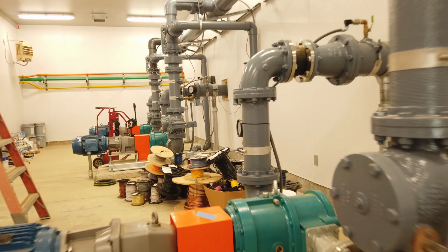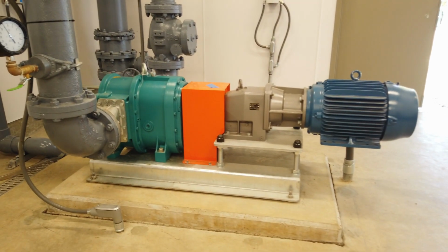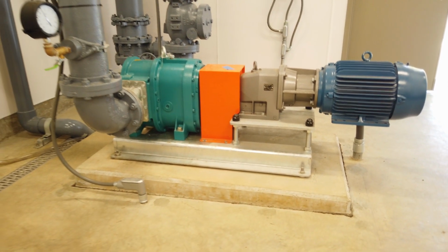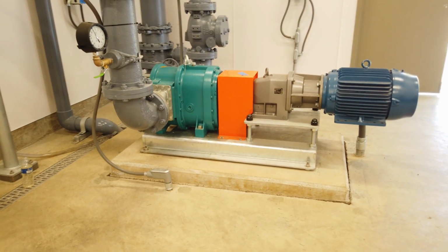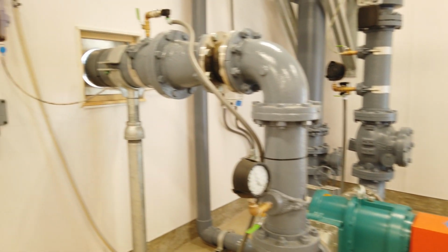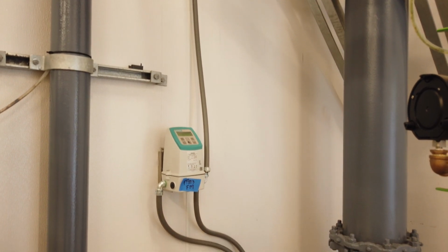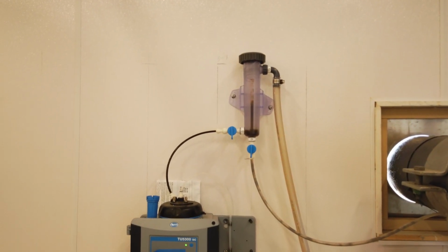We're currently operating 1 MBR tank with a permeate pump that runs about 200 gallons per minute at the low setting. Each pump has a capacity of about 566 gallons per minute. They're all 15 horsepower pumps. Each pump has a flow meter, turbidimeter, and pressure transmitters.